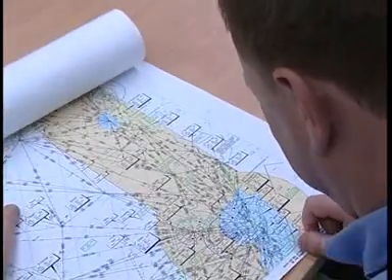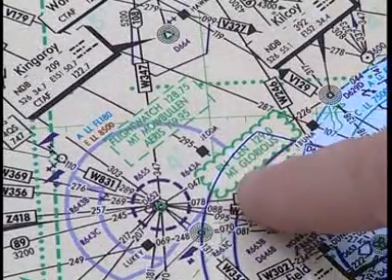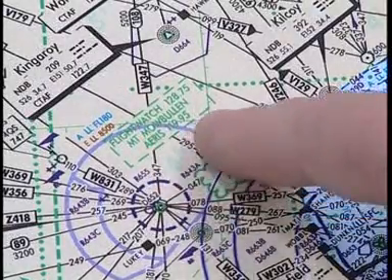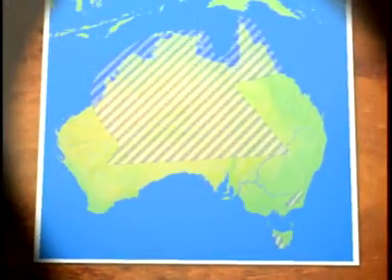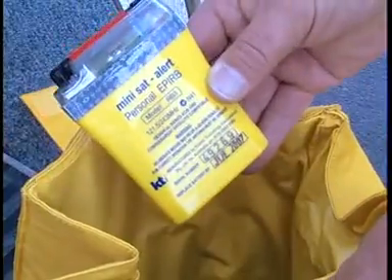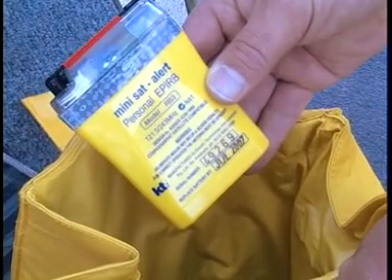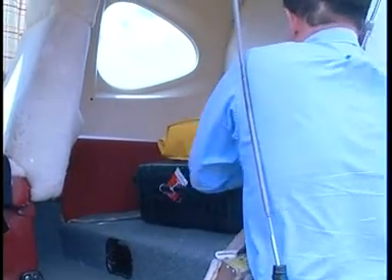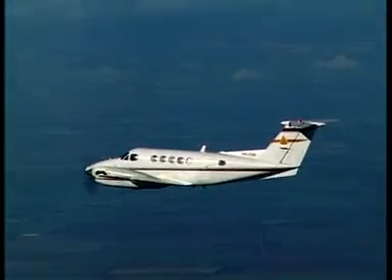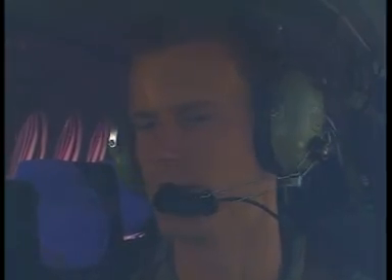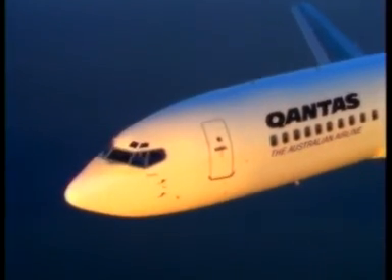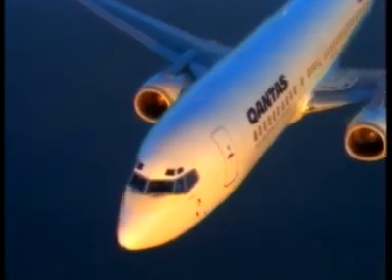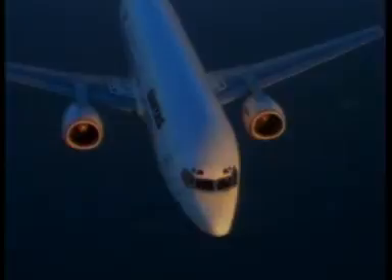Of course, IFR is separated from other IFR in Class D airspace. FIR boundaries and ATS frequencies are removed and replaced by radio frequency boxes that show you the frequency nearest your point. AIRS and FlightWatch also have new depictions. Designated remote areas will be removed from the charts. Everyone carries ELTs these days, but it's important to think about suitable survival equipment every time you go flying. There is a new transponder requirement for everyone operating above 10,000 feet. Regardless of the operation, you will require an operating mode C transponder. Remember, TCAS-equipped aircraft rely on your transponder, even outside radar coverage, for situational awareness.